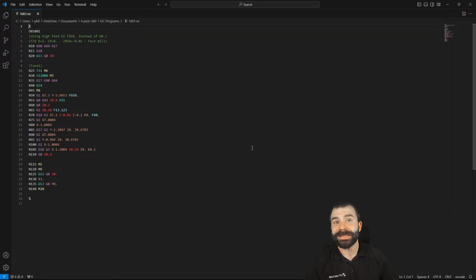Now, the first time all of you post process, you're going to get this window about Visual Studio Code, and you need to download and install it, right? Now, as you can see, I have posted my G-code. I have my G-code to run, and that G-code is lovely color-coded. Again, this is a recommendation to anybody of all levels: once you install Visual Studio Code, you would have to post a second time, and it will open. Now, if it doesn't open the second time, you need to check that box, open.